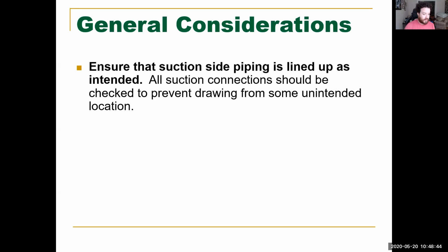So when you turn that pump on, it needs to go somewhere. With kinetic pumps and centrifugal pumps, as we talked about, you can leave that discharge valve closed the entire time. Eventually the water inside will boil, and that will become a problem, but that's hours down the line. Within seconds of a positive displacement pump not having anywhere for the fluid to go, you will have breakage. Pipes will bust. They'll pop through those flanges, it's instant.